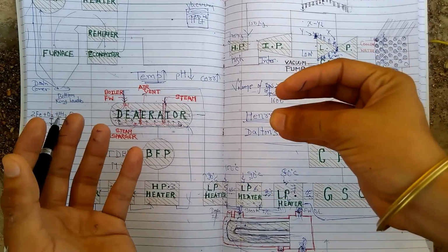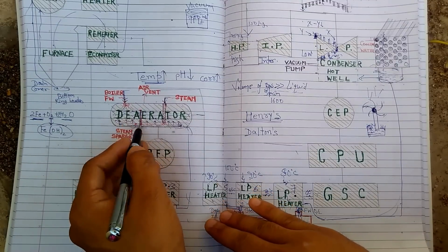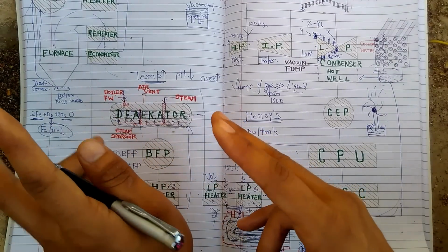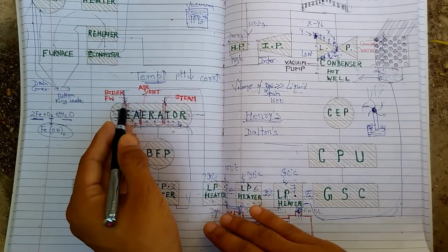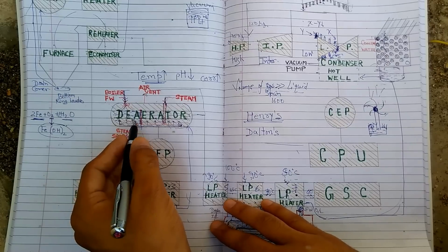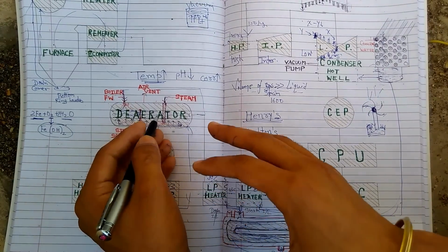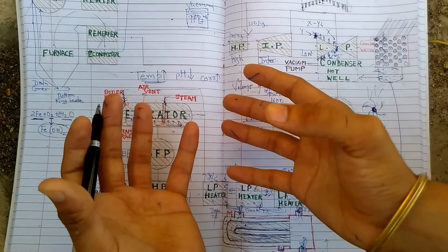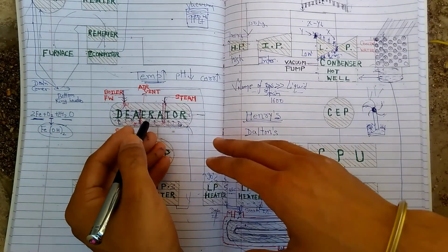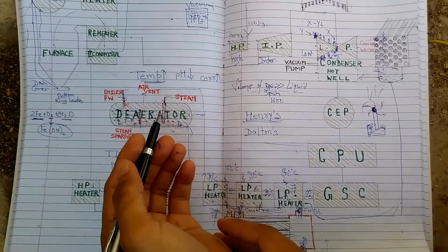Okay, and what it'll do, it will increase the temperature of this feed water. I generally have a baffle plate to bifurcate the deaerator in two parts. In the first part, my boiler feed water will be sprayed and it will get preheated, and after that the preheated water will go into this section. In this section, the steam injected into the water will increase its temperature, and if I increase the temperature, the solubility of my gases will decrease,